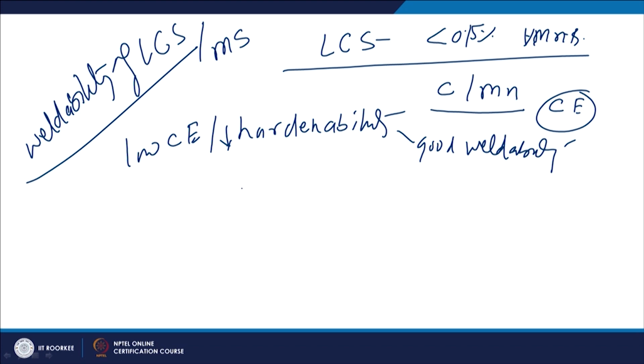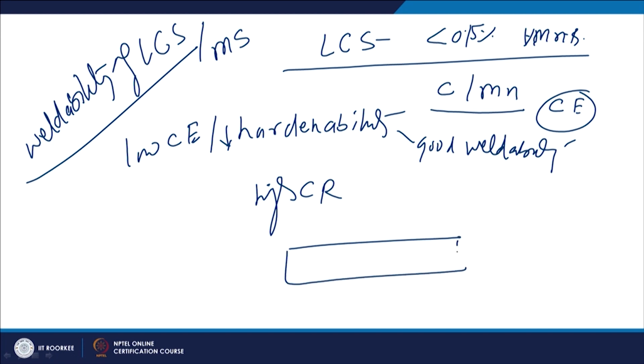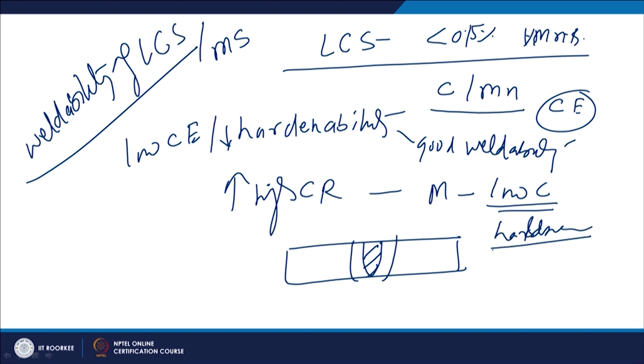because even if there are very high cooling rate conditions experienced during the welding, both in the weld metal or in the heat affected zone, which may be leading to the development of the martensite, this martensite becomes of the low carbon content, and that is why the hardness of such type of the martensite is not very high.